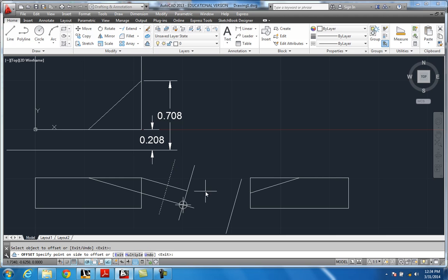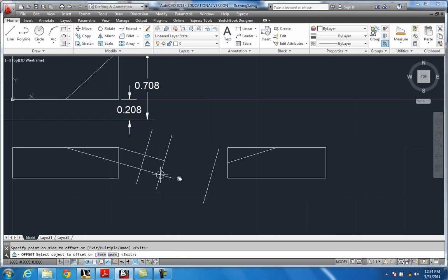Catch this point to there, and all you have to do is just extend this line on down off this point. And where this one shoots to, this line, it's another point, and we have all the data we need to shoot this line across and call that our edge view. So this is our edge view. This right here is the edge view of this line here.